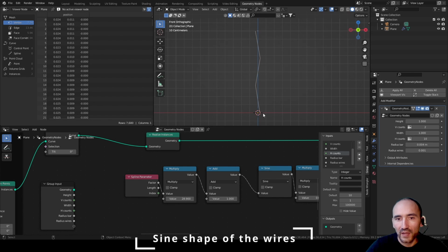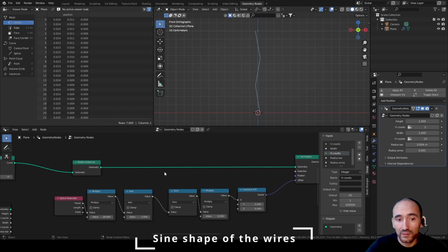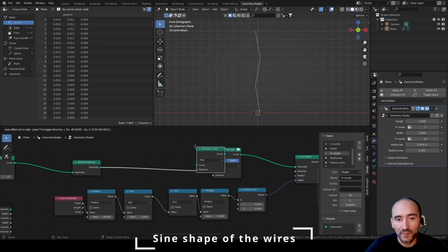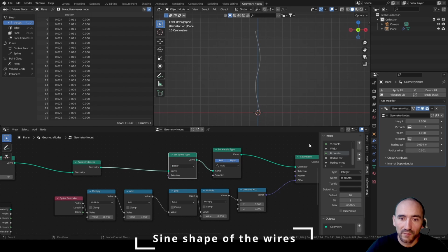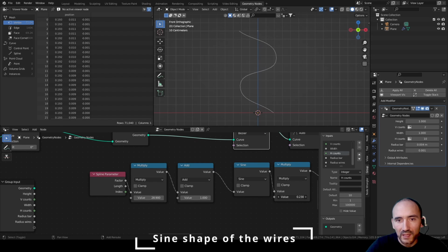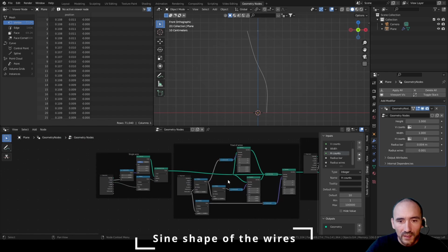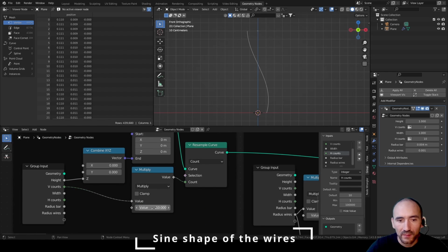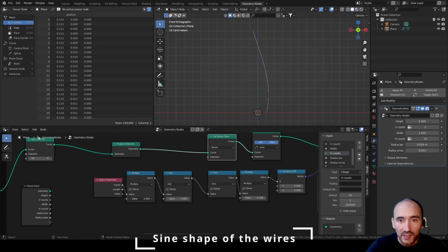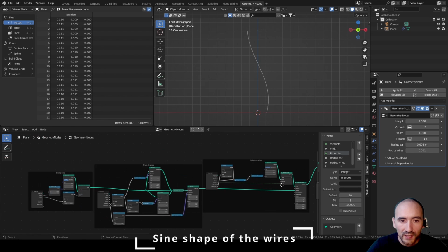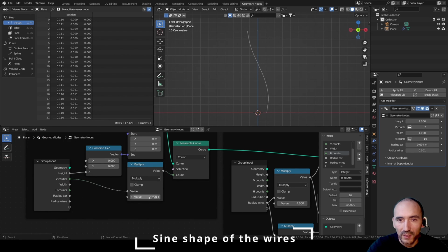So you can see this behavior, and now we could get a better result if we set the spline type of this curve to Bezier, and set the handle type, to see the shape better. Now we want to have the line go from here, go through the center of the axis, and then to the other part. So we have here 2 frequency, so we can increase this shape a little bit, and we have to decrease the frequency. We can set a height number of this single line, maybe 10 for example, and not 2. Now we can decrease or increase this value a little bit. 10 is too much, so we can use 4 or 3 for example.